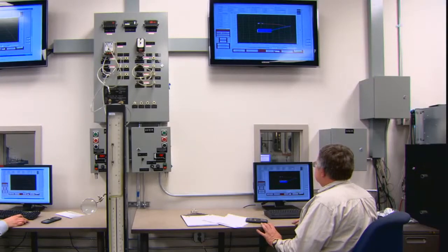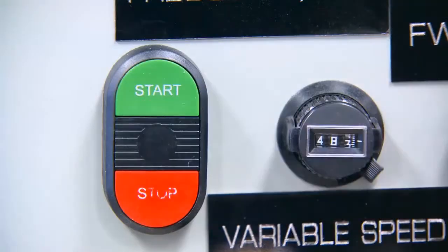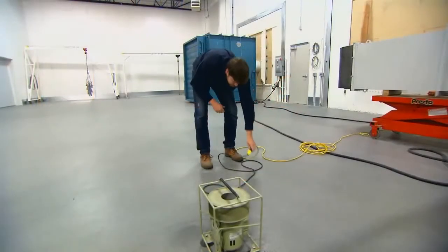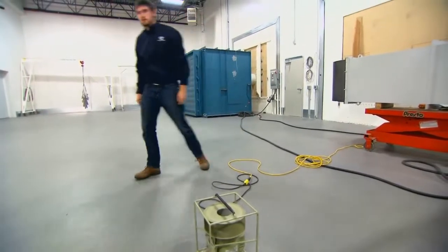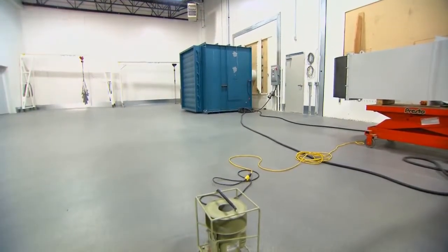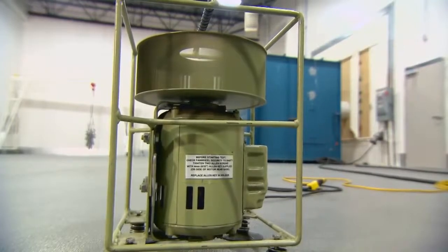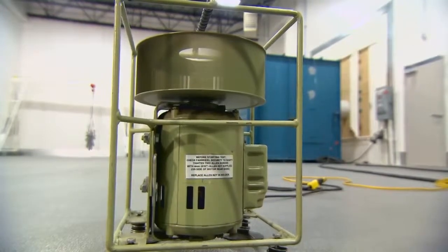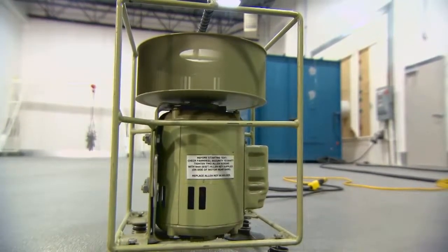We also have sophisticated instrumentation to acquire the necessary data to establish the performance and reliability of our products. We use the reverberant room method to determine the sound power level of our fan. This method utilizes a small fan called a reference sound source for which the sound power is calibrated. Once the sound power level of a fan has been established, we know that that is the level of energy that is being radiated by the fan.